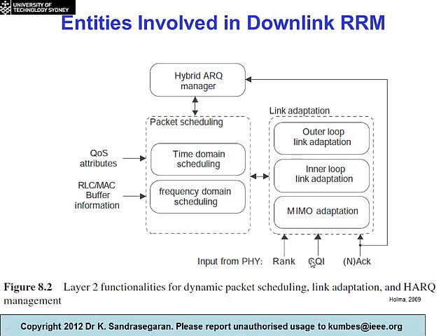We have the CQI, channel quality indicator, that comes in from the UE, and that is used for downlink transmission. It also sends rank information. It sends an ACK or a negative acknowledgement for the packets that it received, and these are used for link adaptation. If you get a negative acknowledgement, it goes to the hybrid ARQ manager, which has to retransmit the packet that was received in error.